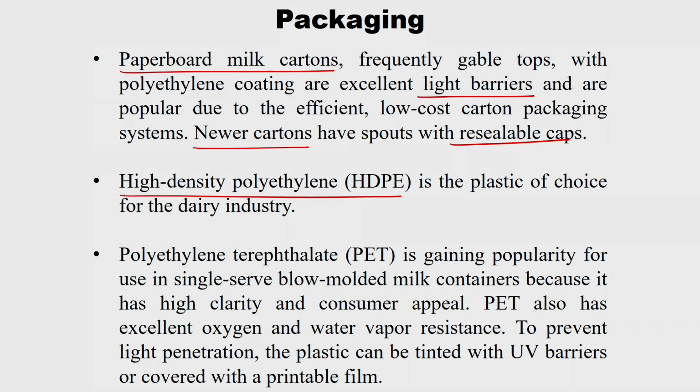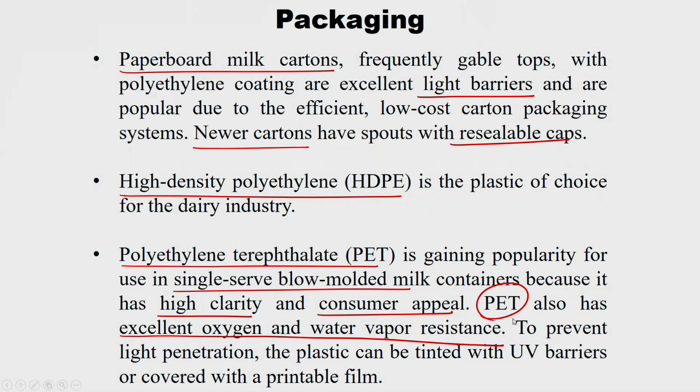This is the choice of every dairy industry, and they also have a separate molding section to produce HDPE based packaging. PET jars are also gaining popularity because of single serve blow molded milk containers, because of their high clarity and consumer appeal, and also excellent oxygen and water vapor resistance. The oxygen and water vapor permeability is very low, and that is why PET is the most wanted one.